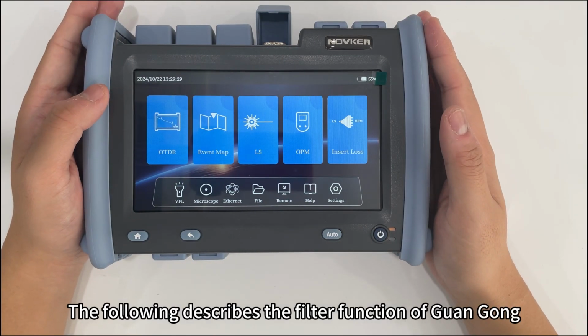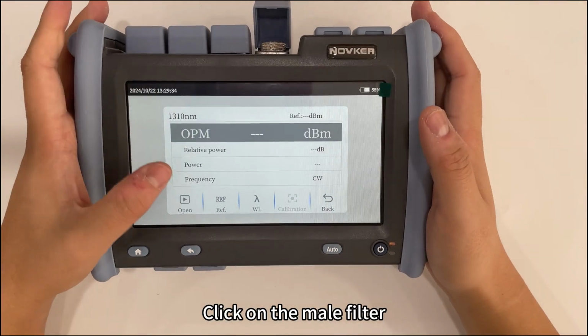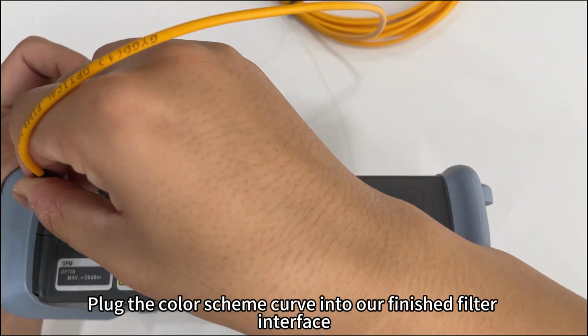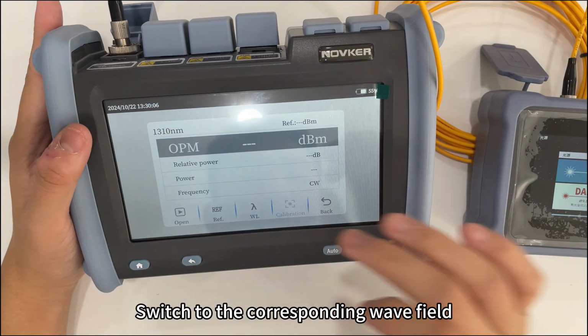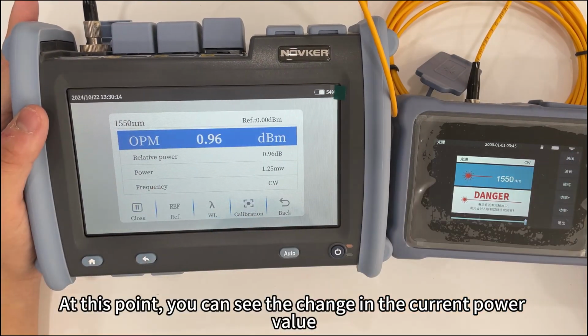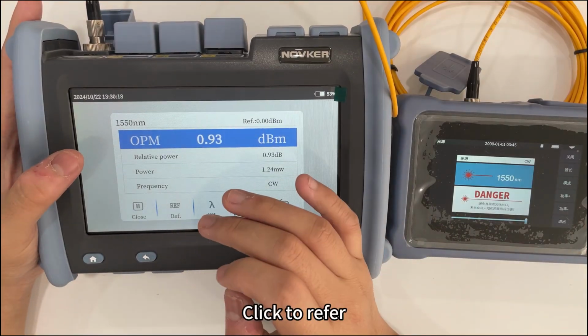The following describes the optical filter function. Click on the optical filter. Plug the fiber into our optical filter interface. Find our light source. Switch to the corresponding wavelength. At this point, you can see the change in the current power value. Click to refer.